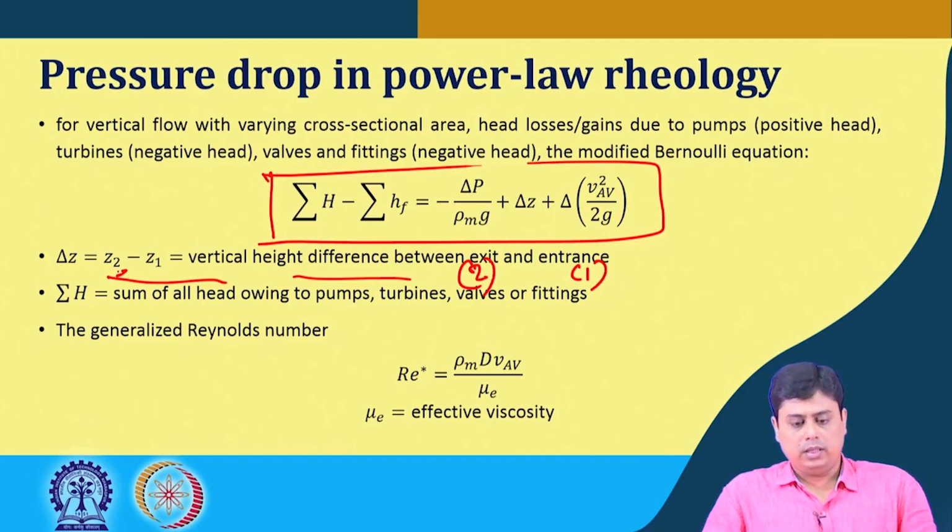Now, what becomes important in friction factor related pressure drop calculation is the flow regime, because is it laminar or turbulent? Depending on that we can consult the friction factor chart or the appropriate correlations to find the friction factor value.